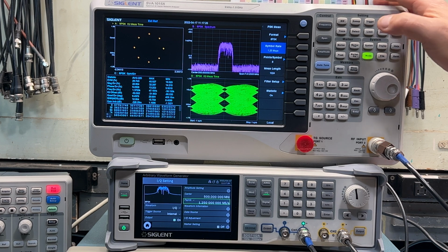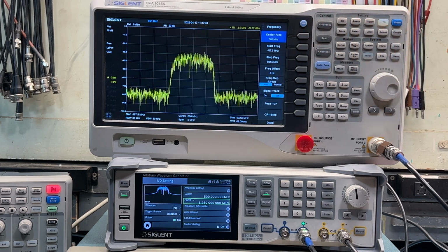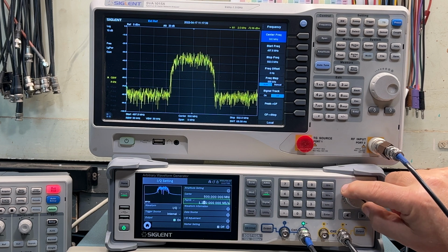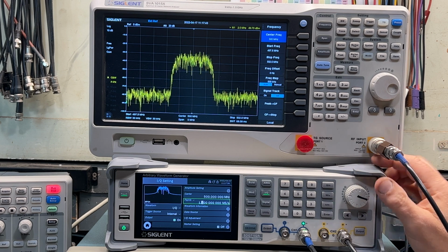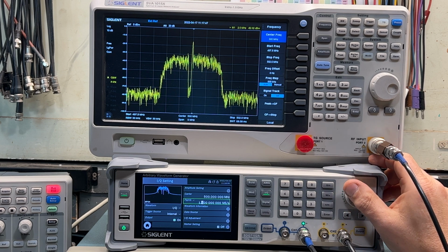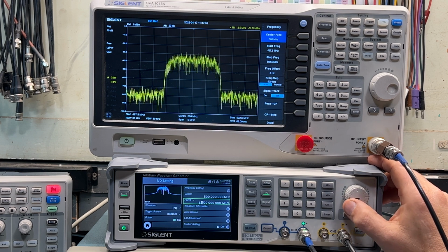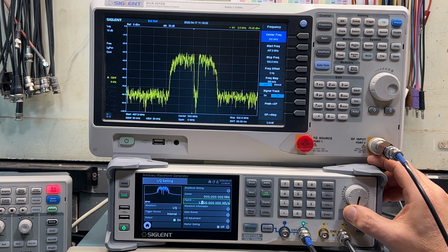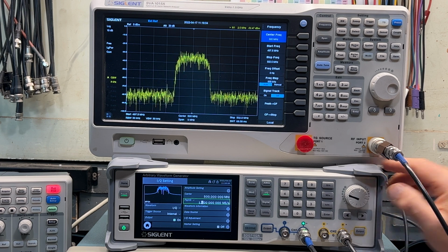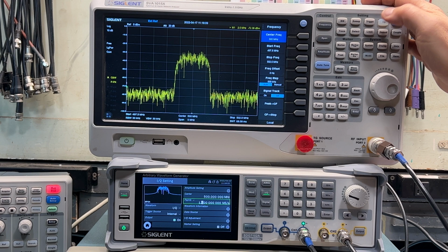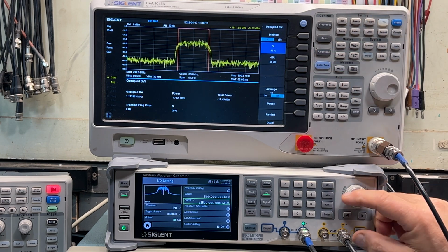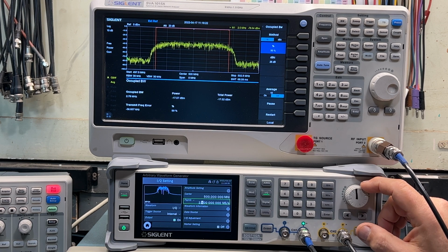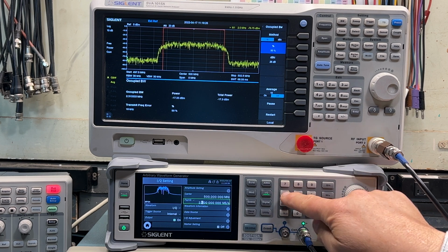Okay, but let's go to spectrum analysis mode. And now here, watch what happens as I change the symbol rate to the spectrum. As I lower the symbol rate, the peak goes up, and it gets narrower. So let's see if we can measure this, just for the hell of it. Measure occupied bandwidth. There we go. So here I can change the symbol rate, and it will measure the bandwidth that the symbol occupies. So let's try a different waveform.